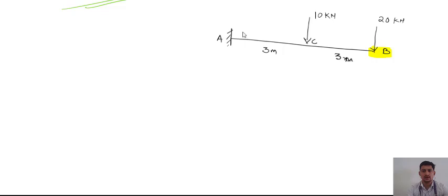So how will you calculate the deflection? I have already told you, when you have been asked to solve the numerical using the unit load method, you have to apply a unit load at that point where you have to calculate the deflection. So while proceeding to the numerical, first of all, you have to calculate the reaction using the external loading.